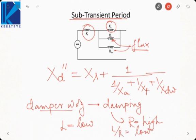But in case of field winding, what is the purpose of the field winding? To generate the flux for the machine operation. Since it generates the flux, its inductance must be high and resistance must be low. Why should the resistance be low? So as to reduce the losses in the field winding. So if inductance is high and resistance is low, L by R of the field winding will be high.